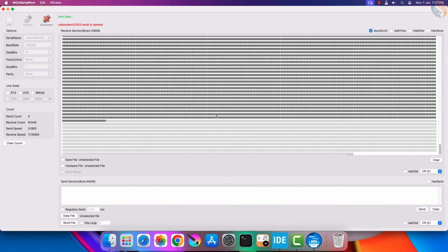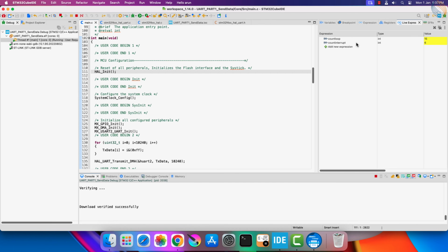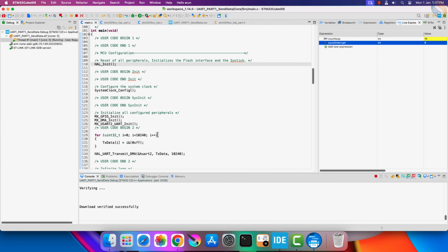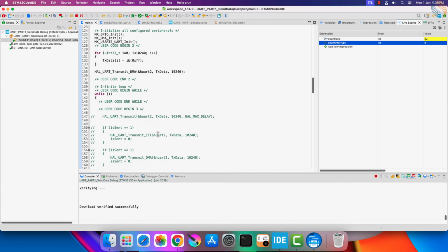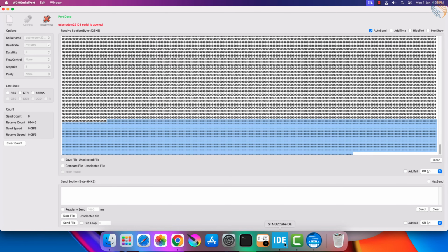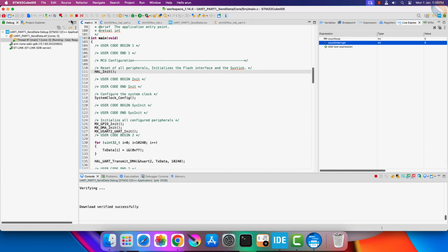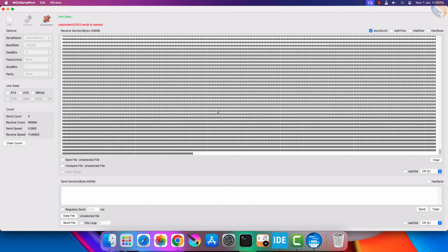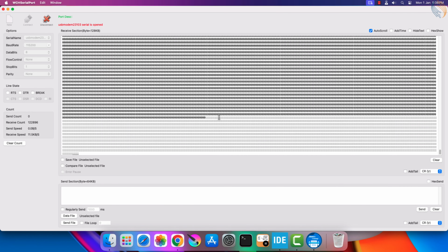You can see the new data is being received by the console. And the DMA stops in the end. The interrupt counter has been stopped while the loop counter continues to count. The data was loaded as we programmed it to do. We can use the DMA in circular mode to transfer large data, whereas we can still have smaller buffers and load the new data in the runtime itself.